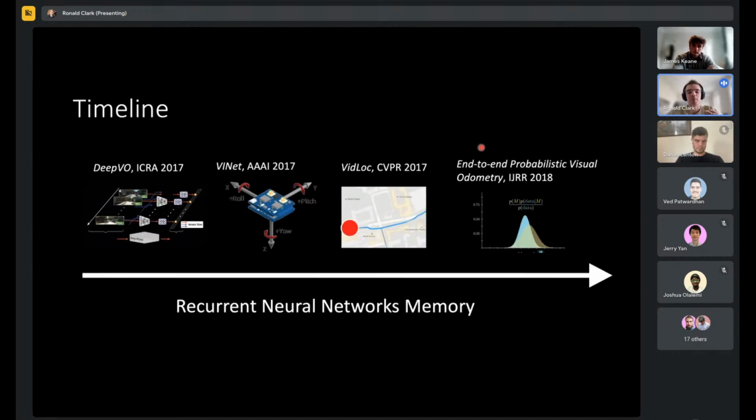Great. So with DeepVO, VINet and ones like that, we were talking only about the motion or the location of the device. But we're also quite interested in what is around the robot or the device. So instead of only estimating the motion of the device, you can estimate the geometry of the scene in a joint manner, because these two variables tie together quite nicely in something known as structure from motion.